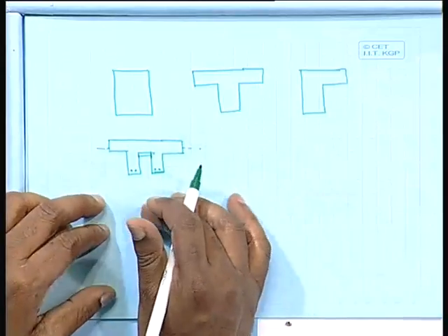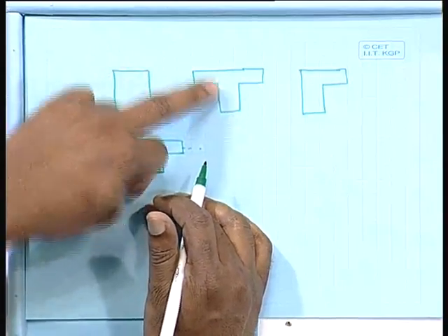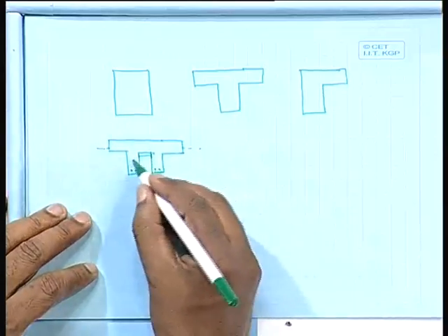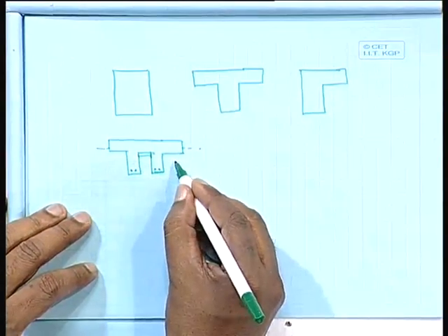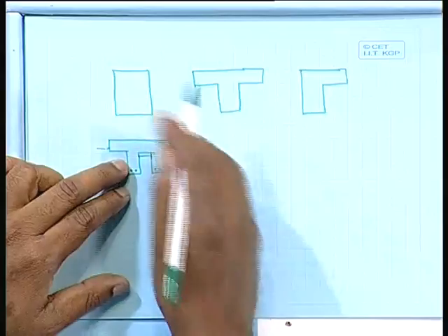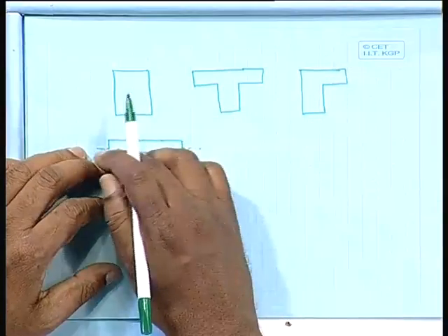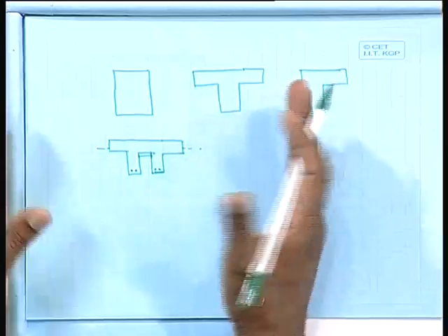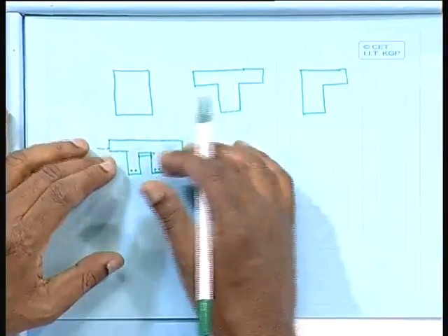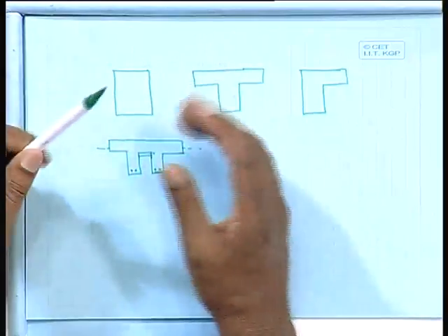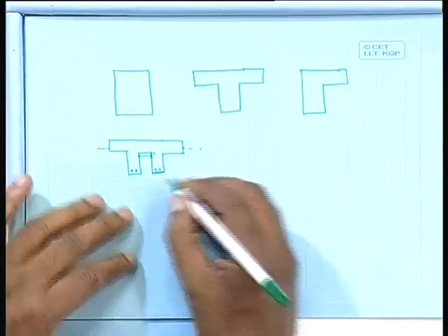So this is nothing but a T beam, or again you can come back to that one. Otherwise, if the neutral axis falls in the other option, then you have to do that calculation. So in this case it is always preferable that I keep the neutral axis within that limit. That is one way of the tricky solution, providing the solution within that limit, so our calculation and other things will be easy. So this is one problem.